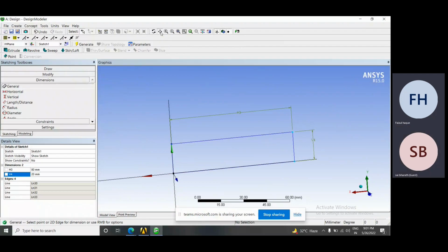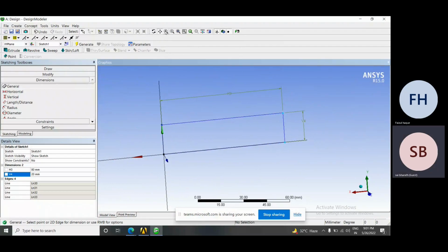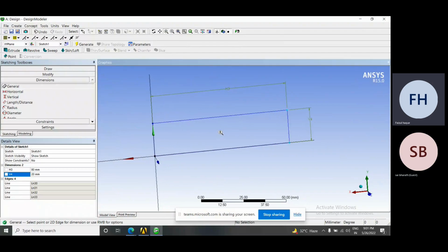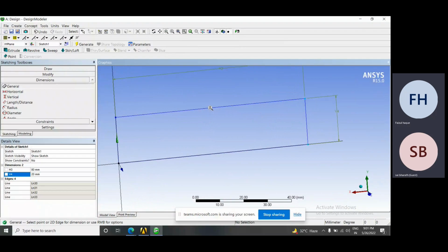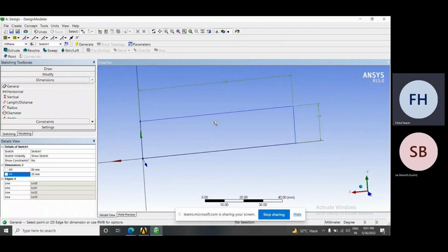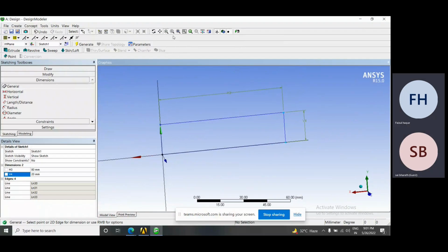Just click the left mouse button on the panning option and you can pan the window. Click on the magnifier window icon, then click the left mouse button, and if you move the mouse upwards, then zooming in occurs. And with the left mouse button clicked, if you drag the mouse downward, then zoom out occurs.